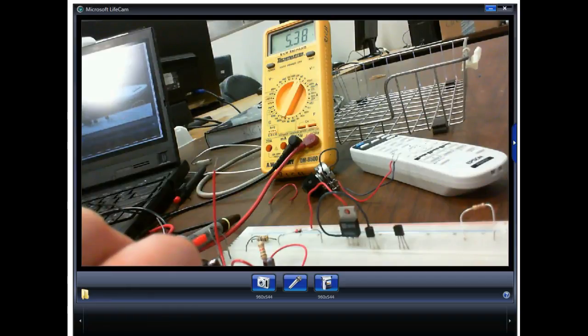Of course, why did it go up? Because we lost that 500 ohm resistor over there, right? Understand that? But we lost that 1K resistor over there. So we calculated, if we use 33K and 39K, and divide it by 52K and multiply that by 10, it came up to give us 5.4 volts. So this is almost perfect now, right?